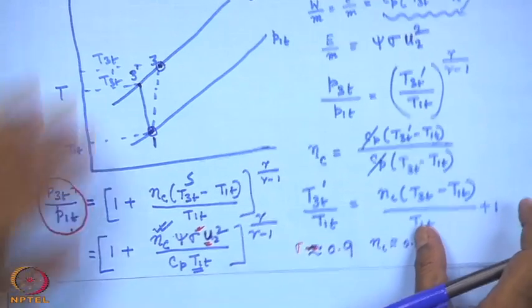Now, I will come to a very important thing of the compressor, not centrifugal or axial compressor. As I told earlier, since the compressor handles fluids which are compressible in nature, they are gas, they are not liquid, their bulk modulus of elasticity is little less. So, depending upon the flow velocity, the density changes, and if the change of density is appreciable, flow is compressible.